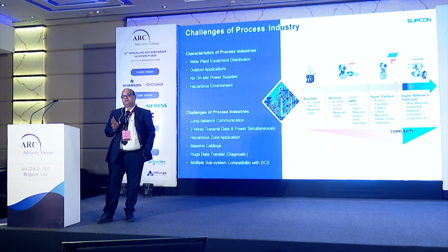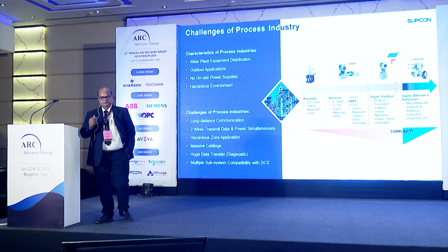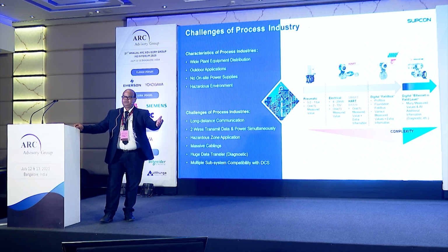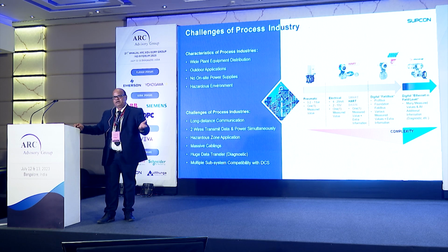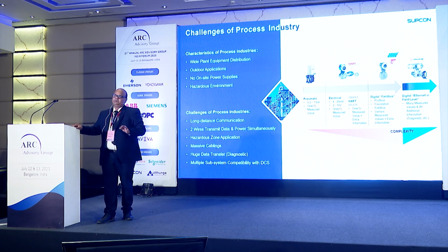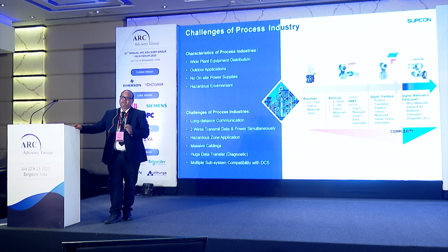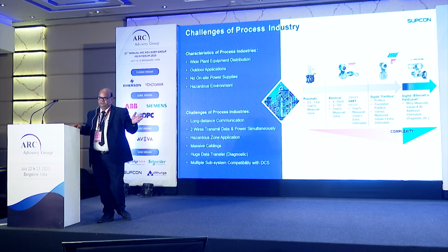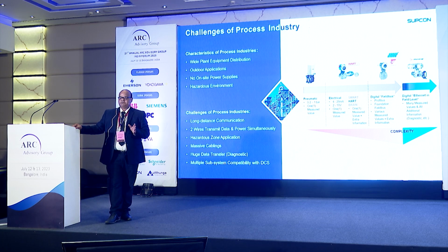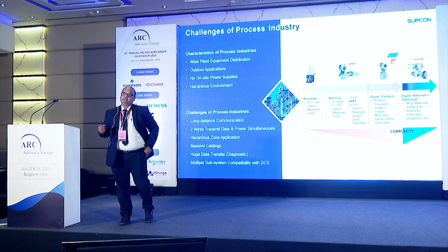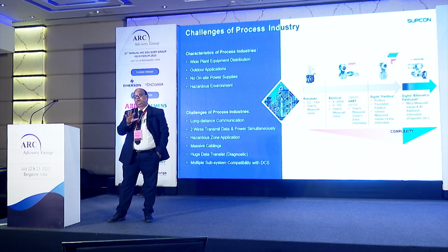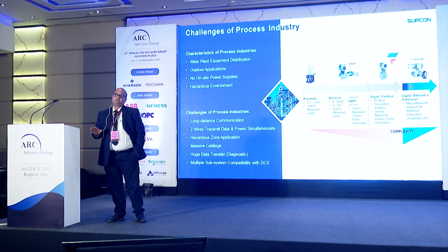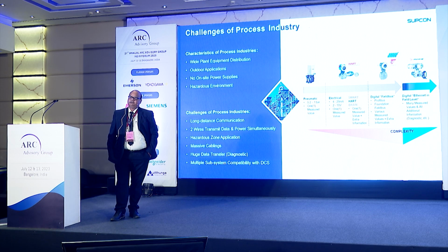All the parameters are monitored by the CPCB and the Pollution Control Board. For that, we have the FGCS system, the flue gas cleaning system. It means the control and instrumentation technician or engineer has to work from -9 meter to the 45 meter of the chimney. Everywhere there are instruments and all the parameters are very important. As this technology is new to India, we have only 5 to 7 plants working properly in the waste to energy sector.